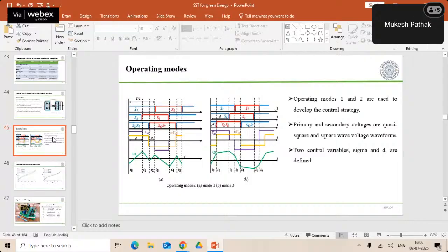I'm saying the basic fundamental of SST is a controller only, AC to DC, then DC to AC. It is a system where the transformer is accompanied by a converter on both input and output side. Yes, sir. The conventional transformer is only a core and winding, whereas here you have core and winding in the form of a high frequency transformer plus a lot of power electronics.